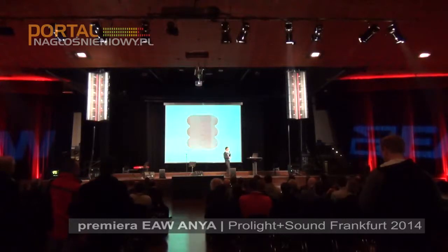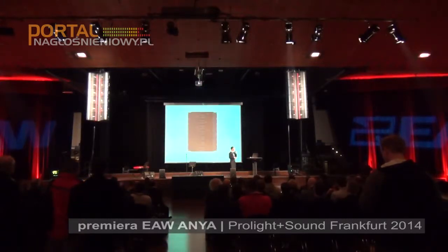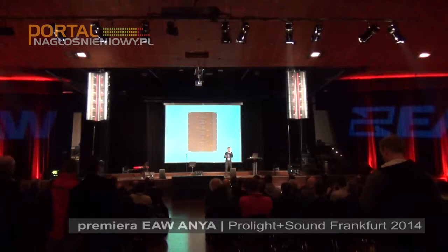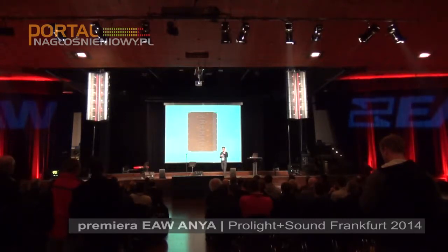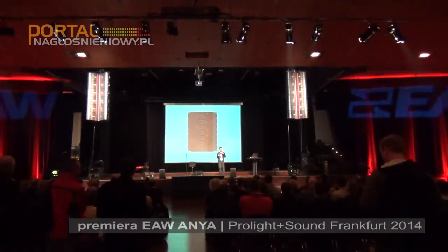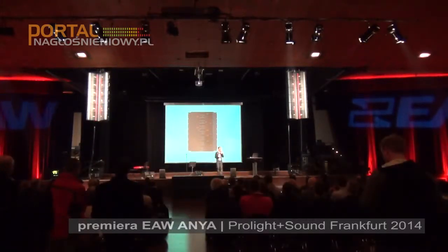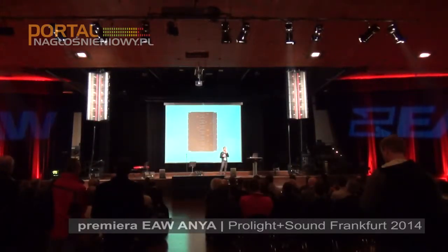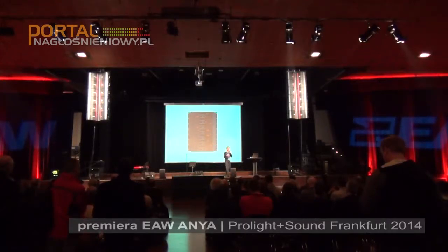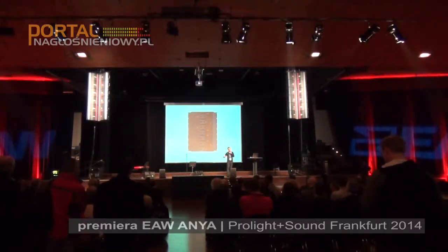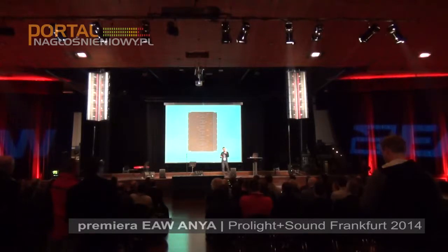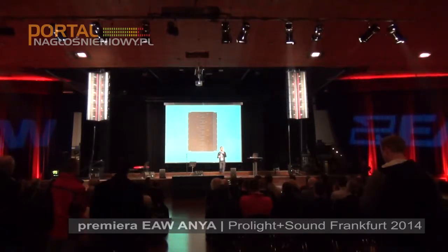The second technology, the CSA technology that we introduced in the AX series in the mid-2000s, thereabouts, randomizes the size, shape, and location of the mid-frequency apertures to have minimal impact on the high-frequency wavefront. Since the 2 subsections are sharing the same horn, getting them to combine, we need to pay quite a bit of attention to how that's done.